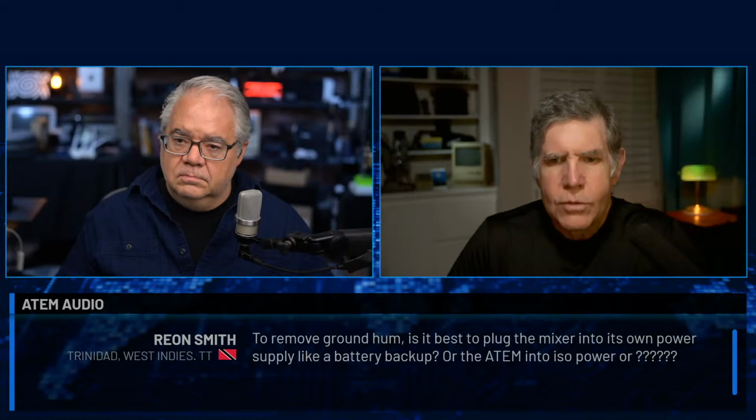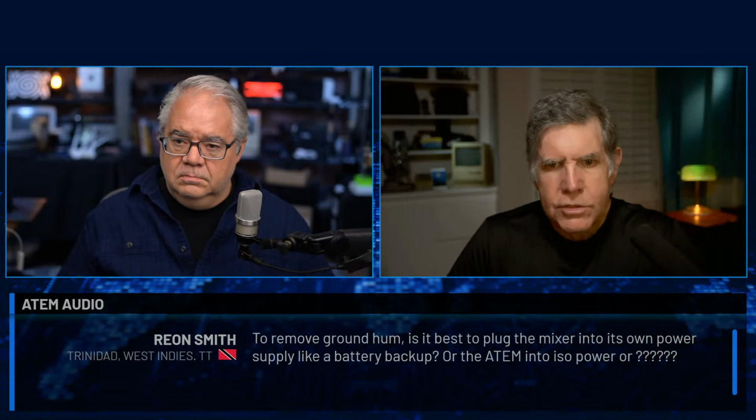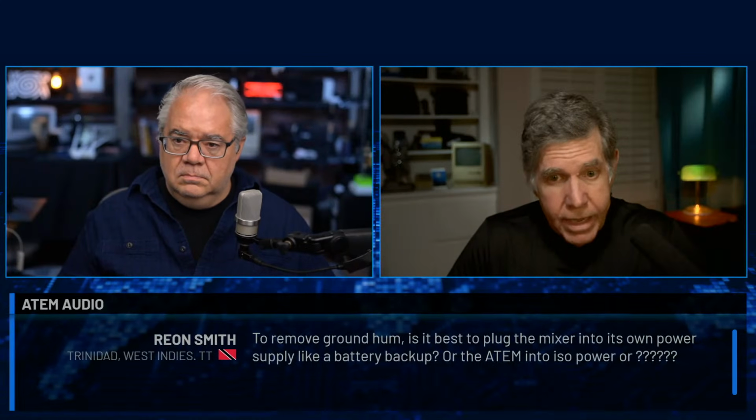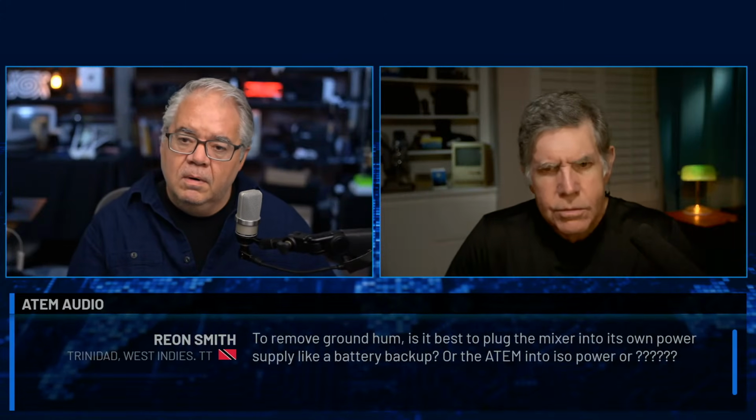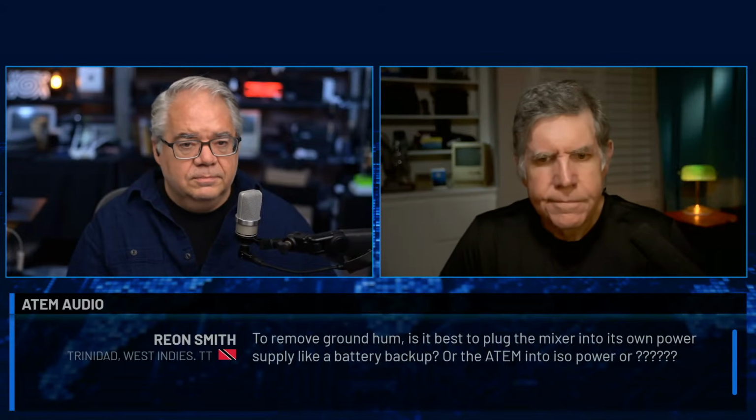Next question. Next one comes from Rian Smith in Trinidad, West Indies. Again, this time, to remove ground hum, is it best to plug the mixer into its own power supply, like a battery backup, or the ATEM into ISO power, or is there another better solution? Courtney? Yeah, running everything off battery is one way to remove AC hum. The ATEM minis will run off of 12 volts DC, so you could go that route to remove all ground hum. Otherwise, plug everything into the same AC source that has a common ground.